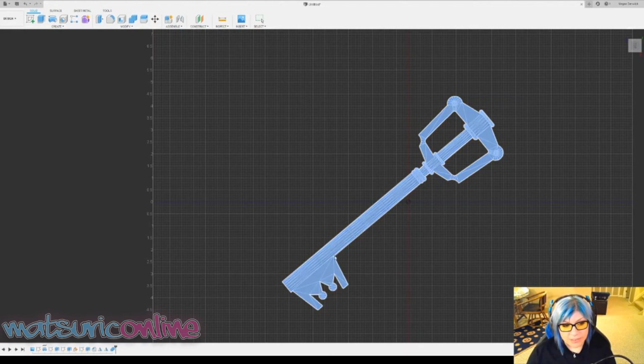You can change your refinement to low. So as you can see, there's a lot less triangles. You can go to high. So there's a lot more triangles. Or you can go to custom and you can custom do your surfaces and change things. And that one is if you're a lot more advanced. Honestly, the high setting is great. I've never had issues with it, but if you really want that high quality mesh in certain areas, I suggest doing the custom.